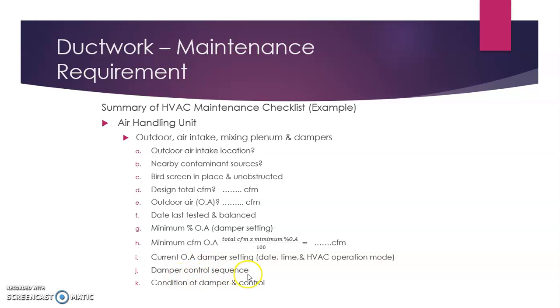So the damper control sequence, you have to know how the damper control sequence works, and the condition of the damper and control, whether it is in good condition or broken. So you have to look into those particular things.